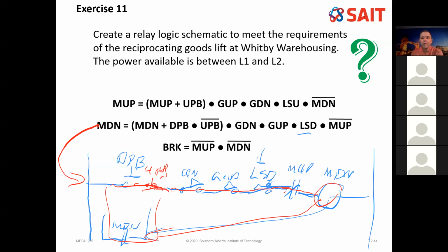And if you don't want to solve it with an Arduino, you can put the same formula into an Arduino and it'll work. Or you can put it into a Raspberry Pi, or into any computer system you want. But the Boolean expression that we described here is the mathematical description of the control system, right? So this is the correct way of designing a control system. Understand the problem, define the inputs and outputs, build the Boolean expression that works with those inputs and outputs, and then turn it into whatever it is you're going to solve it with. In our case, ladder diagrams.